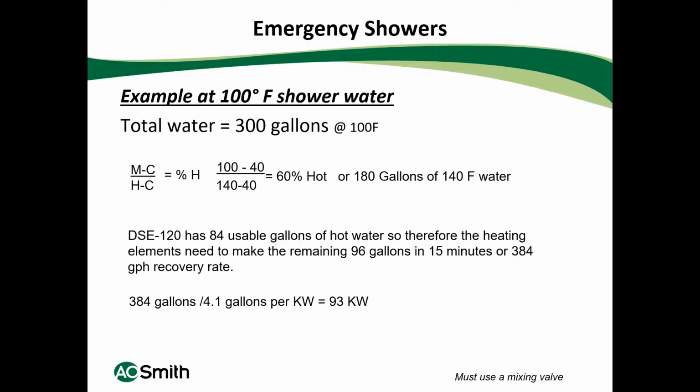So that number would change if of course we're going to store water at a higher or lower temperature than 140, but we assume 40-degree water going in, and you're storing it at 140, so that's a 100-degree rise. So 1 kilowatt will heat 4.1 gallons of water per hour. So on the emergency showers, a good question came up.